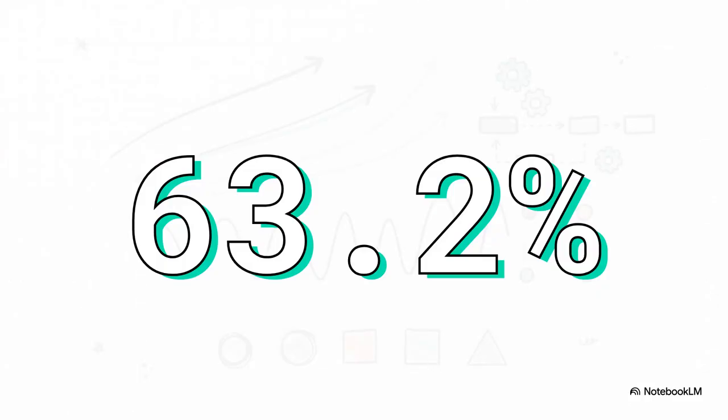So, you can now visually spot process order just by glancing at the trend shape. You know, the immediate rise of a first order, the bounce of a second order, and the flat start of a high-order system. But visual reading is only half the battle. How do we precisely calculate the time it takes a process to settle?